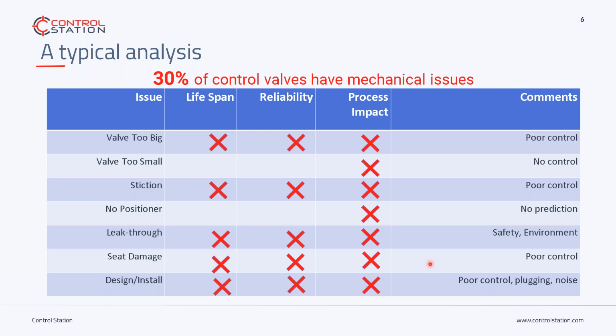Damien, what about you in your experience? Yeah, no, absolutely. The seat noise is something I always thought about. Noise on a valve: if you can hear the valve, that means it's working really hard. The material passing through it is going through a very small opening, and if there are any corrosive or erosive components in that, noise means abrasion. That's the reality of it.